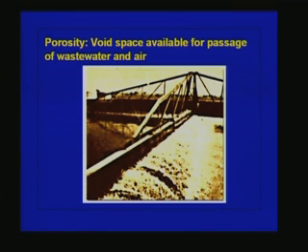The reason is, if you have a high specific surface area, the amount of biofilm present in the system will be very, very high, because the microbial film will be growing over the entire surface. So as the specific surface area increases, the biofilm area as well as the total volume of biofilm will increase. And we all know that in any biological system, the workers are microorganisms. So naturally, if you can provide more microorganisms in the system, the efficiency will be very, very high.